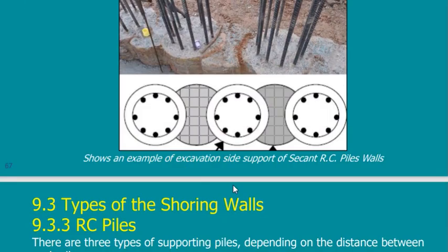To do this, I do it in two stages. The first stage, I drill these piles. You see these dark piles? They are not reinforced. I just drill and put cement with bentonite and so on. So it is just a plug.